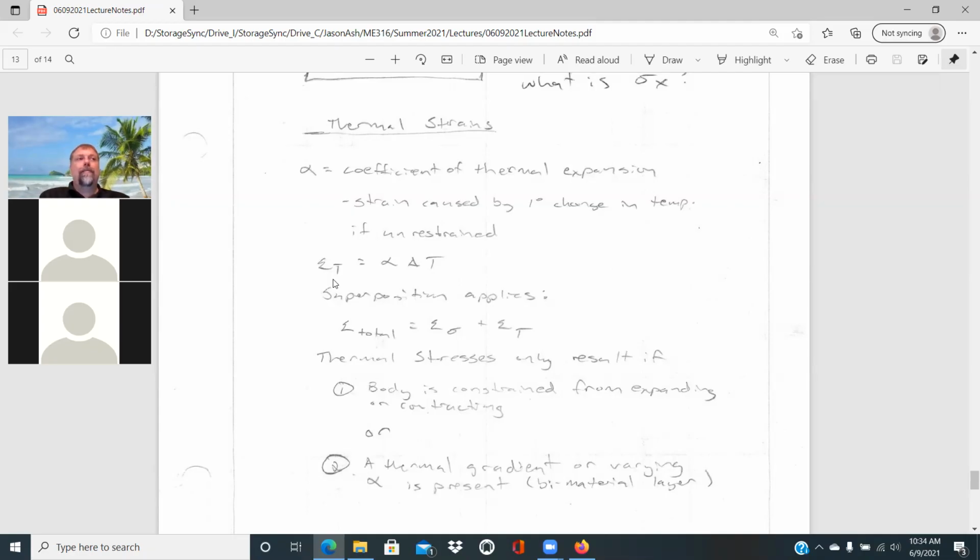And then likewise, if you have different materials bonded together that have different coefficients of thermal expansion, they are then in an epic battle with one another. One wants to expand more than the other, and they end up warping and deforming and building up thermal stresses in that process. And so those are all things that really need to be considered when you are dealing with situations of large temperature changes and what effect that will have on any thermal stresses that build up.